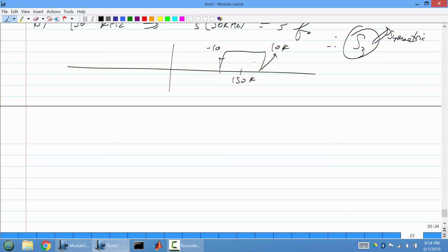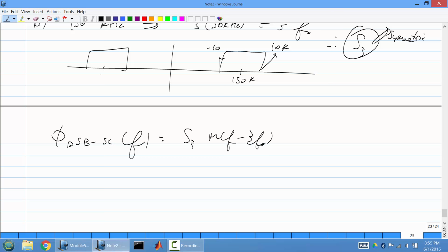Once you have this, what you need now is to represent the Fourier transform of this. So this is what we need to get: double sideband with carrier. I need to concentrate on the third copy, which is at 3 times omega naught. So I need S3, and then I also need 1 here as well, plus 3 omega naught here, 3F.